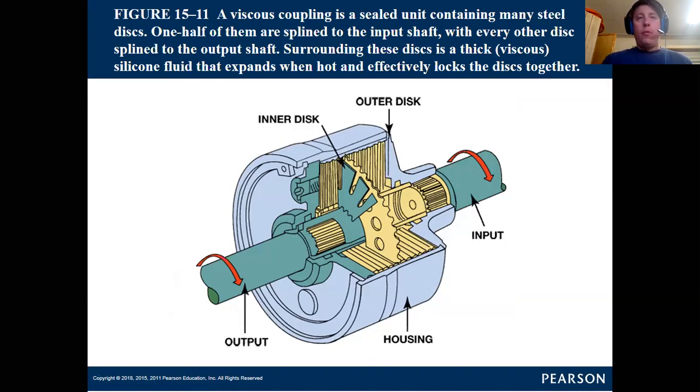You can't have full-time four-wheel drive and not call it all-wheel drive, because it's always engaged. So the difference between part-time and full-time is we incorporate some sort of differential component in the middle of the vehicle between the front axle and the rear axle. Not all-time all-wheel drive vehicles are a 50-50 power split between the front axle and the rear axle.